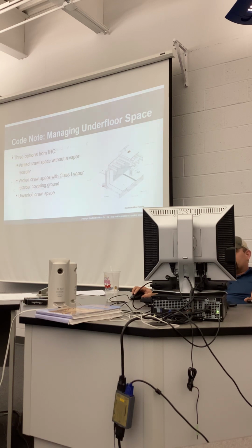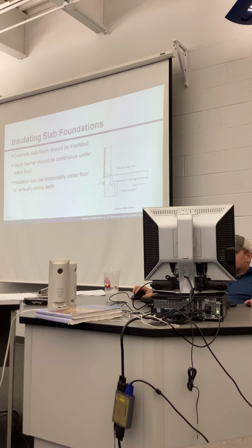It's really good. So this is how you can insulate your floor system, or you can run insulation underneath your slab. You can break it with, this is called a thermal break, or you can insulate underneath and down, and then insulate on the outside. I don't like this way. Don't get me wrong, it works. Why wouldn't I like it?